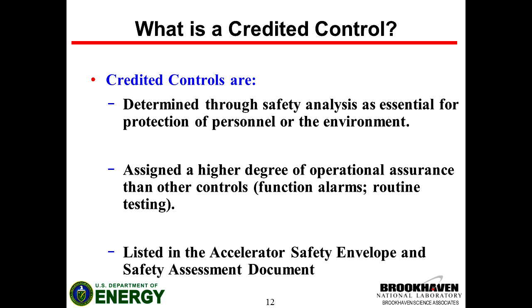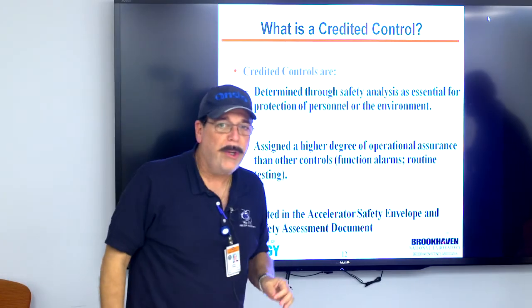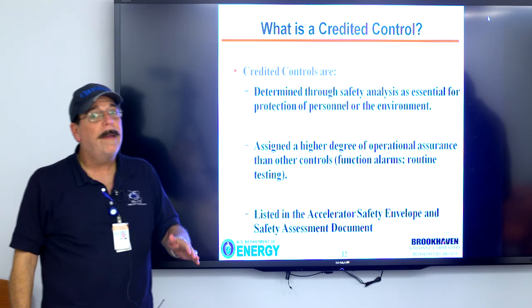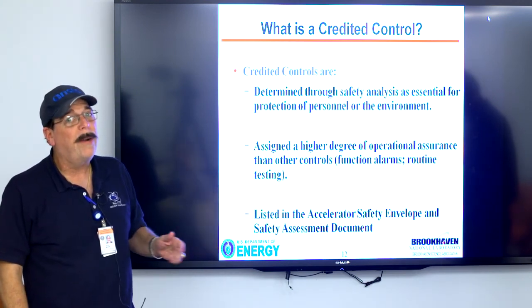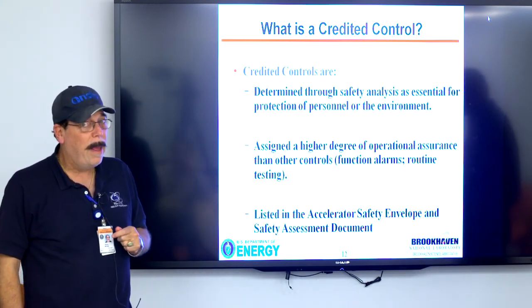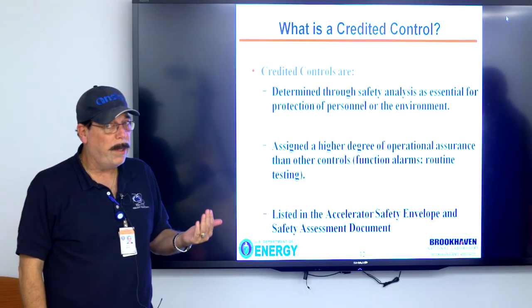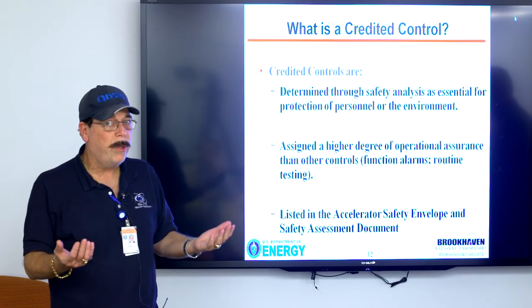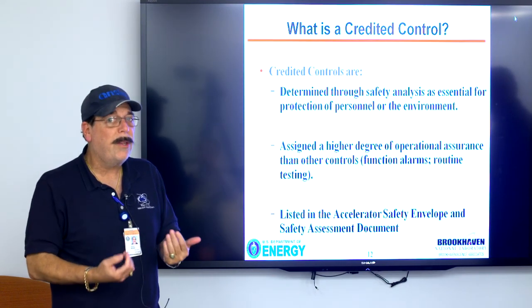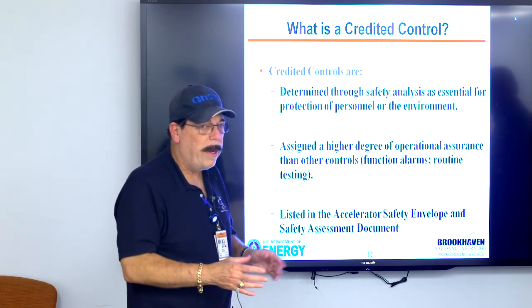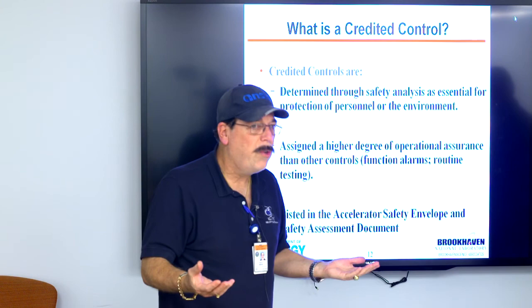One other point that you did make that is not up on the slide is this idea of configuration management, that we have to assure ourselves before we start up our operations that everything that we say is there has been verified as being there since the last time we operated it, or for the first time we operate it. And we go so far as to actually take pictures of the layout of the shielding to make sure that if we ever have to undo the shielding to reach some component that's hidden underneath it, we're able to put it back exactly the same way so as not to create some unanalyzed streaming issue.